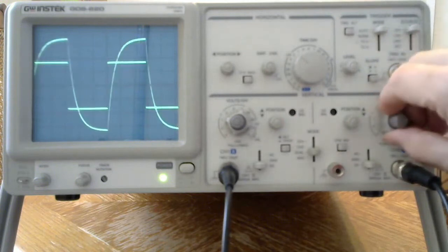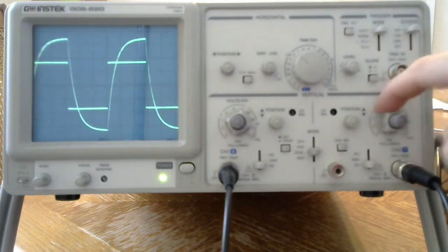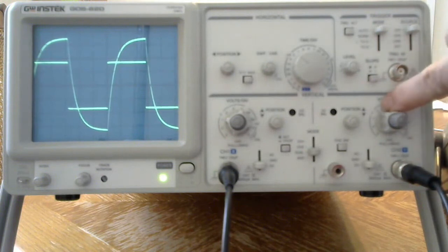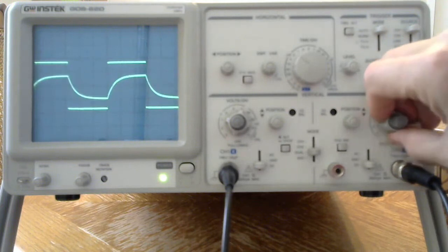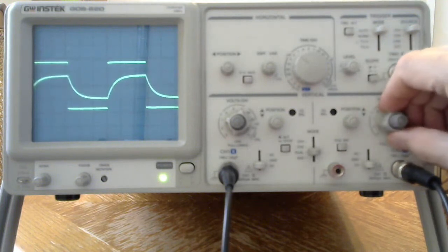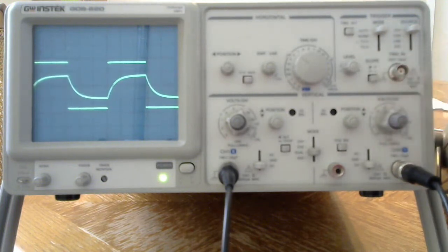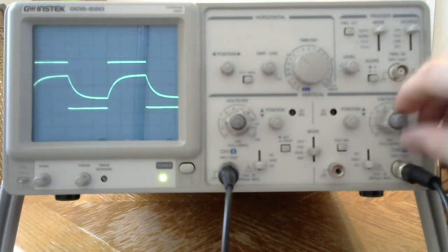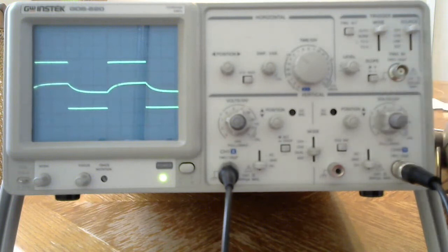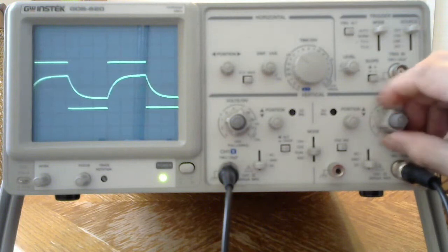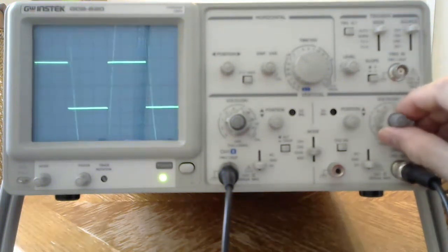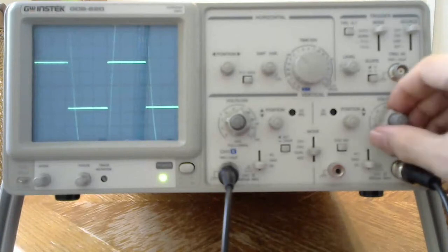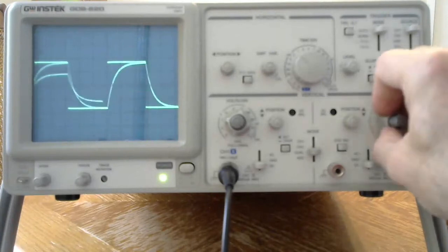capacitor, okay? So by turning this knob, I can read the number of volts per division. Right now it's set to 5 volts per division. Here it's set to 1 volt per division. Here it's set to 2 volts per division. And here it's set to 5 volts per division. So 5 volts per division, 2 volts per division, 1 volt per division, half a volt per division, and there I have 0.2 volts per division. So I'm zooming in as I turn that, right?